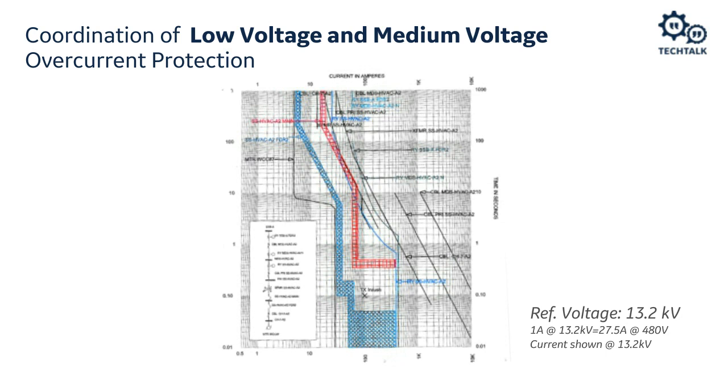The other thing we need to do is, if we look at the little X just above the flat portion of the blue curve, that is the transformer inrush. So for those downstream devices, we will need to be below it, or for the upstream devices, we will have to have a slower tripping time than the transformer inrush. Likewise, the straight curves there are the transformer thermal damage curves, and we'll need to have all of our protection devices set so that we are below the damage curves and we don't damage the transformer.